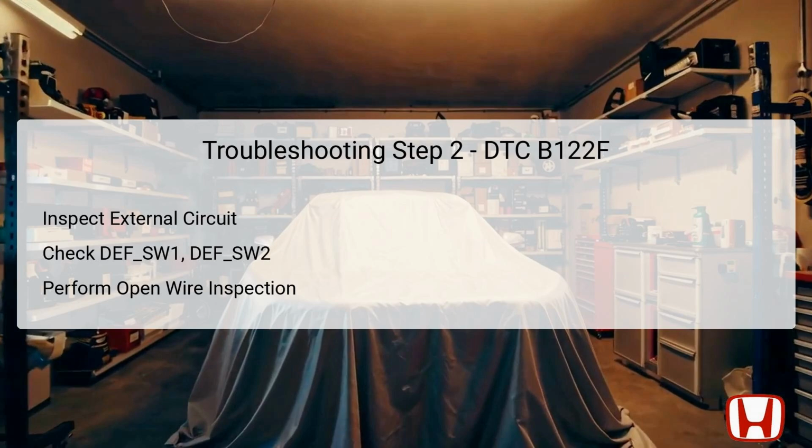During this inspection, technicians will look for any visual signs of wear, damage, or loose connections that could lead to an open circuit condition. Utilizing an ohm meter, it's crucial to check the resistance in the wires connected to the defrost switch. There should be less than 1 ohm resistance in normal functioning conditions. If resistance is considerably higher, or a complete open circuit is indicated, this confirms issues within the wiring.